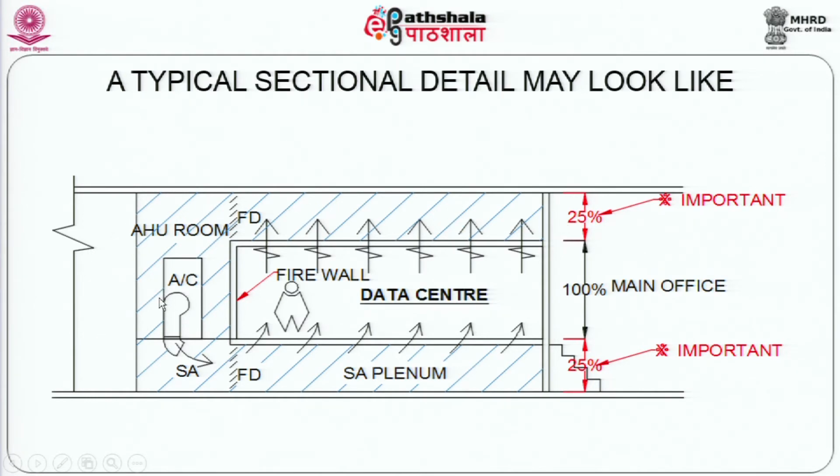So, you have a large requirement of air which is now put into this, and this floor has the normal 600 mm by 600 floor tiles. So, in other words, if somebody were to plunk equipment here, he could just remove the tiles of one equipment, put in a grill here, and you would have a grill here. Let us say this equipment gets relocated here. You close the earlier tile, open up the new tile, and you have a shifted pattern of air conditioning without having to do any mechanical work on your air conditioning equipment.